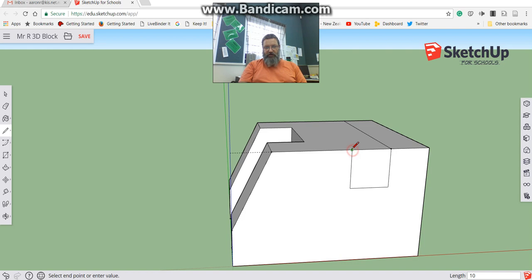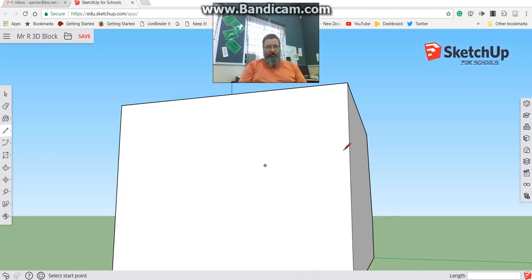So I want to do another line that goes across there, make sure the line is green, type 10, I'm not going to type 10, am I? Oh, it's thinking. I don't want to type 10, I want to type 40 and press enter. There we go. So now I've drawn those lines all the way across. Use that center button again to orbit around.